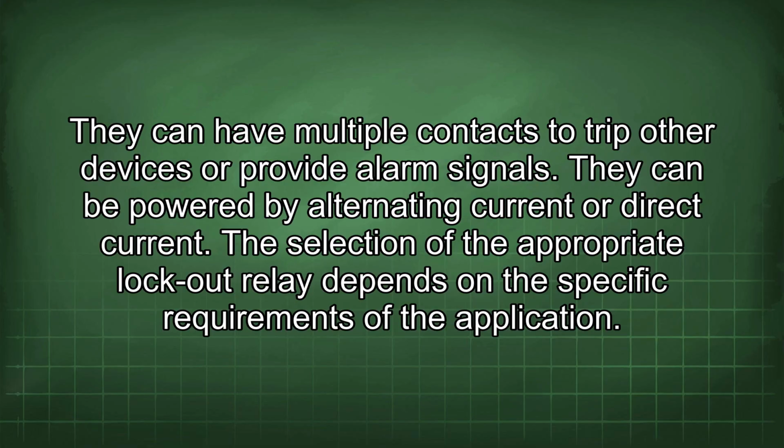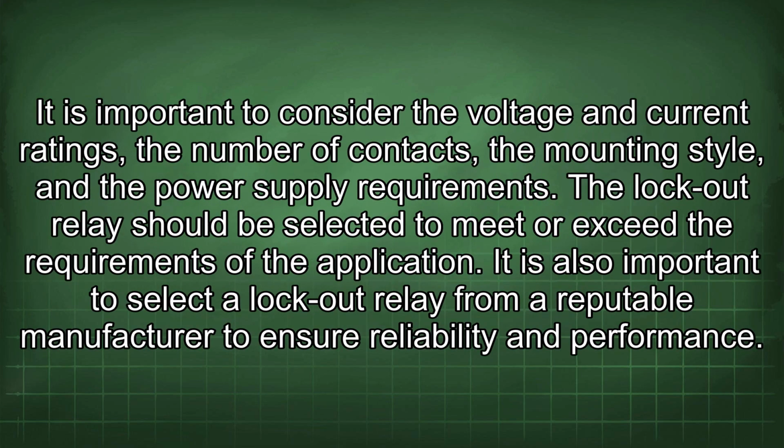The selection of the appropriate lockout relay depends on the specific requirements of the application. It is important to consider the voltage and current ratings, the number of contacts, the mounting style, and the power supply requirements. The lockout relay should be selected to meet or exceed the requirements of the application. It is also important to select a lockout relay from a reputable manufacturer to ensure reliability and performance.